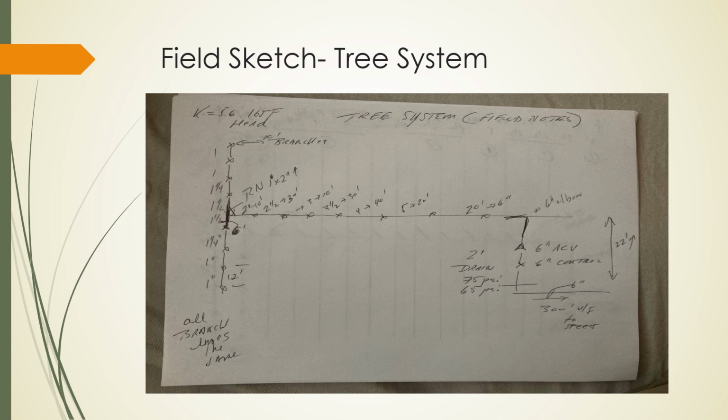And again, I'm using the inspector's test to ensure that that 1 inch line looks like the 1 inch branch, the end line. I'm using the reducers. I'm looking at the riser nipples to establish size. I'm determining that the branches are all the same. So if there's different branches, then I've got to sketch them out. But in this case, all the branches are the same. So once I have that one branch, I'm pretty much all set.